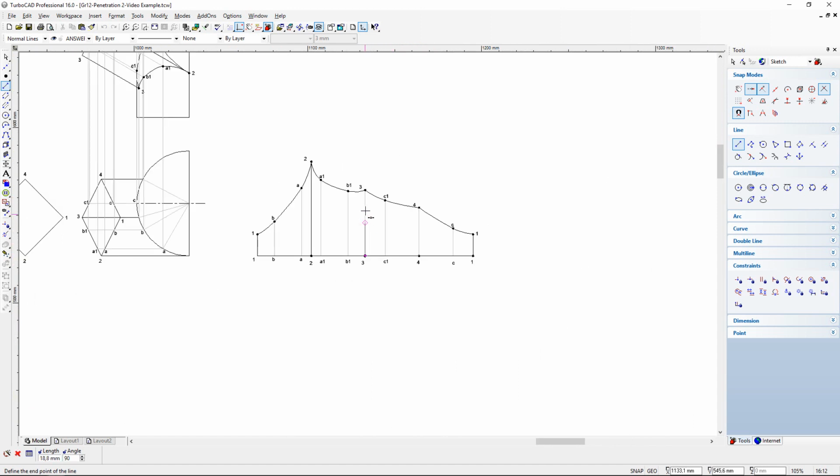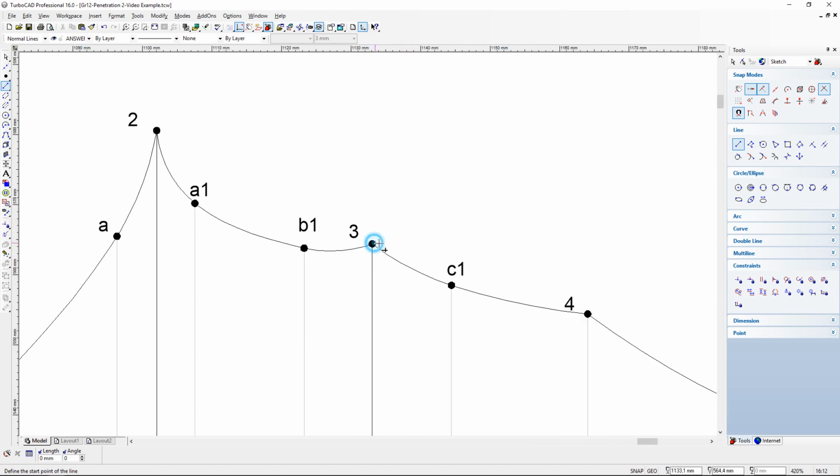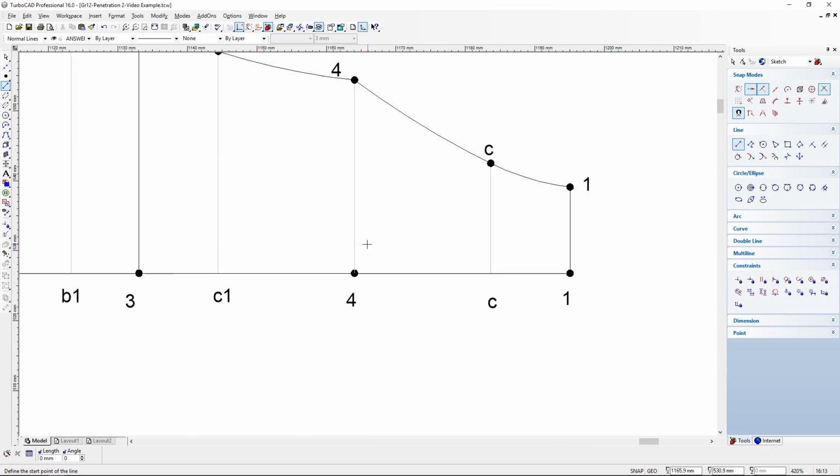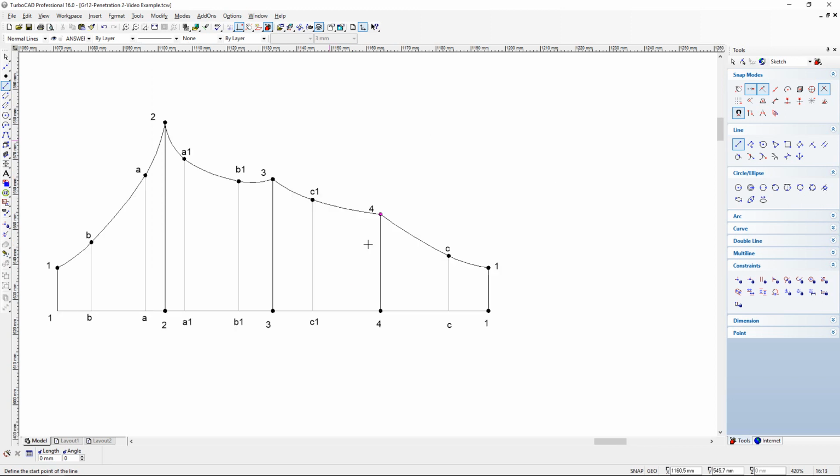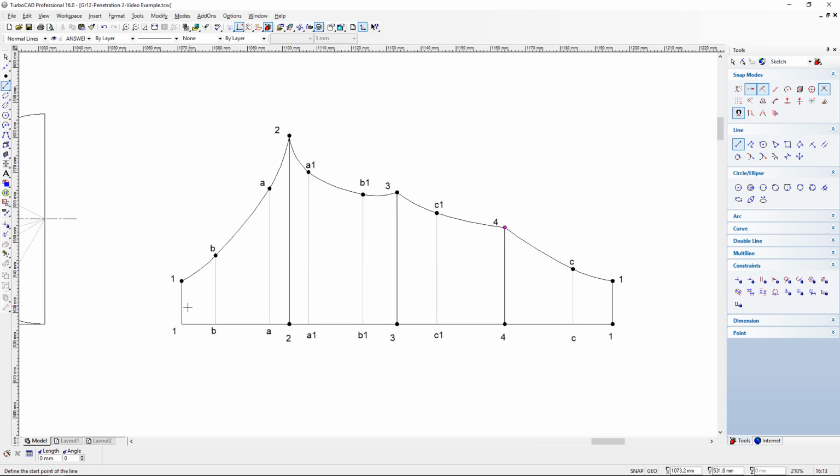Sometimes they draw a fold line there, which means it's a double dash. It looks like a center line but has the double dash line, and I'm just drawing a solid line here because each of my sides of my prism is a straight edge. And there we go. So I've got light construction lines to show my constructions for the points in between number 1, 2, 3, 4 and back to 1. And now we have a perfect and neat development of the penetrating pipe.